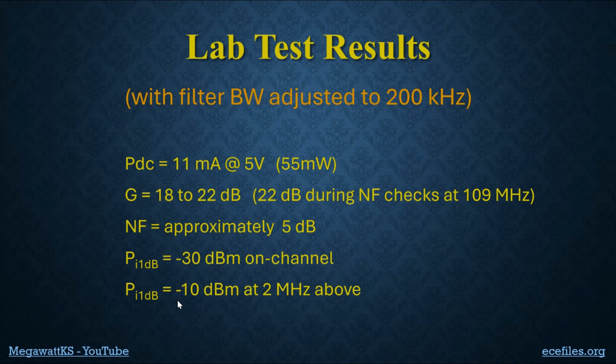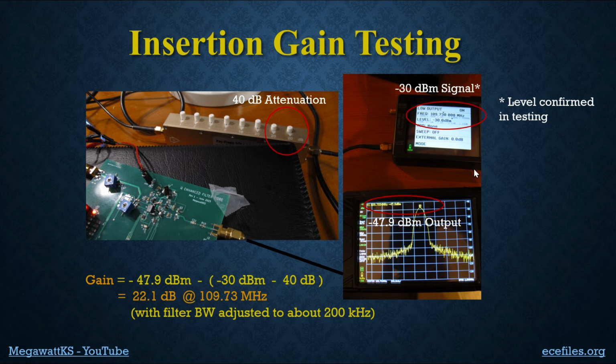And there, it came out to be minus 10 dBm. That's a really strong signal. And I'll show you how we measured these things. First, the gain. Here's the signal generator.